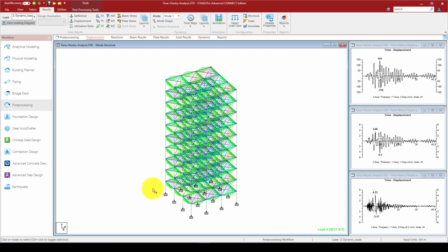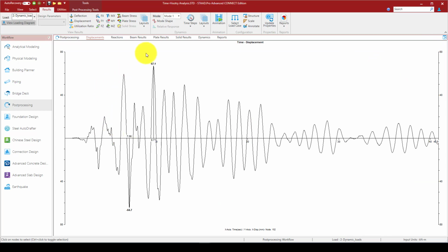So this direction is top direction, and z direction is also small, but quite a large displacement is observed in the x, because we applied the earthquakes in the x direction. So we also can measure it in the bottom, and you can see first floor, second floor, and the program automatically gives you the top nodes, the maximum displacement,